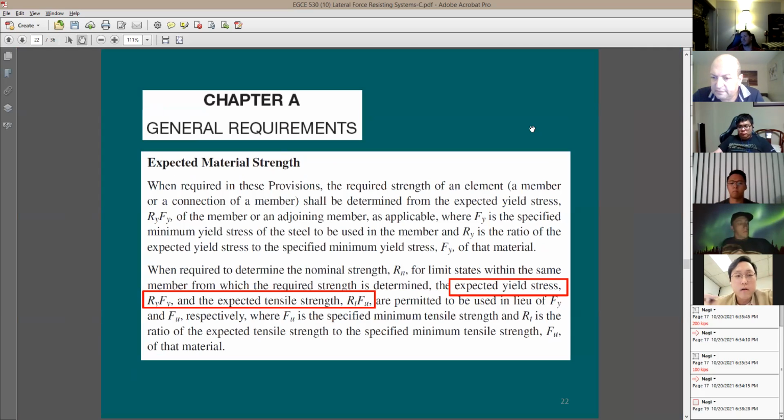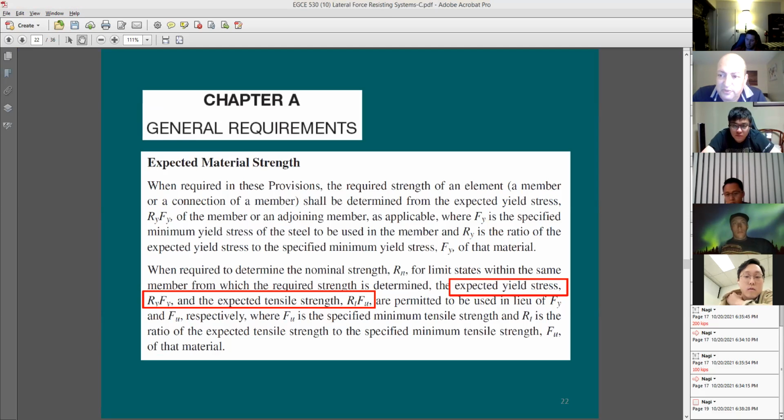You mentioned earlier about EV, earthquake vertical force. When do you have a vertical force due to earthquakes? For all members, all buildings, you need to design for E sub V. The equation for it is simple. It's going to be 0.2 SDS times the weight. Okay, because I'm just thinking earthquake hits laterally. No, you also have a vertical component.